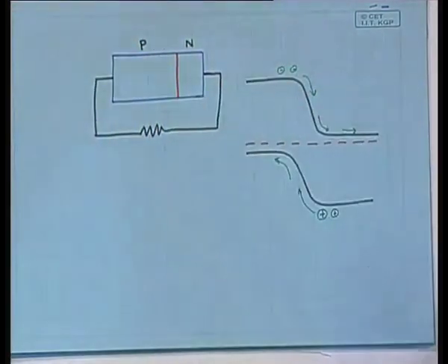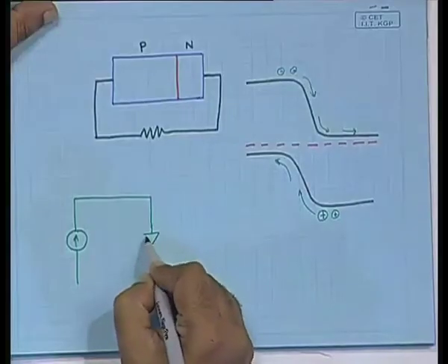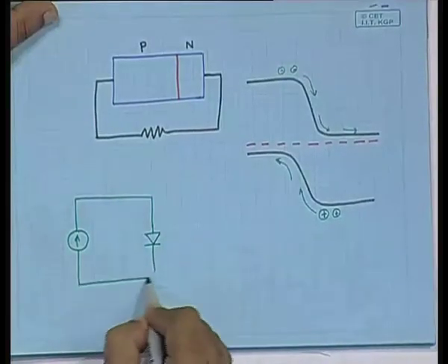So, there is a charge separation and there is a charge recombination going on, since it cannot flow through the external circuit. Now, if we have this balance, that means some amount of charge is separated, creating the I_PH photocurrent, and some of it goes through the diode without going through the external circuit, then your equivalent circuit essentially becomes only this.